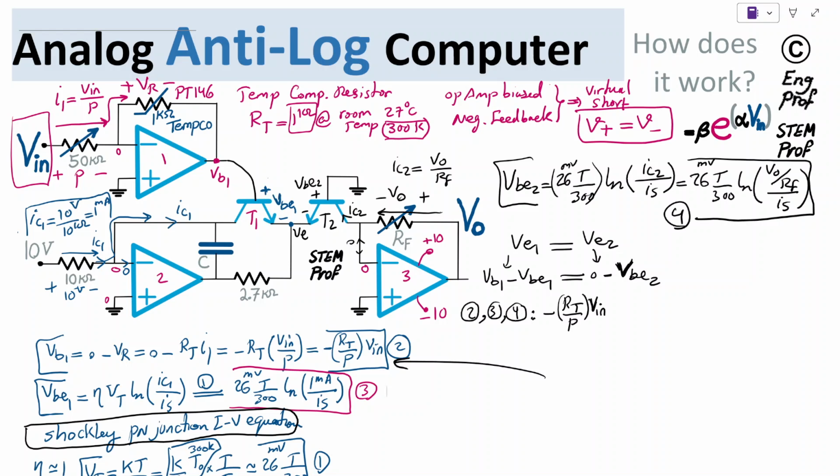And for negative VBE1, I'm substituting for VBE1 from equation 3: 26 millivolt T over 300 log of 1 milliamp divided by IS, equal to, for minus VBE2, I'm going to substitute using equation 4, which says VBE2 is equal to this.